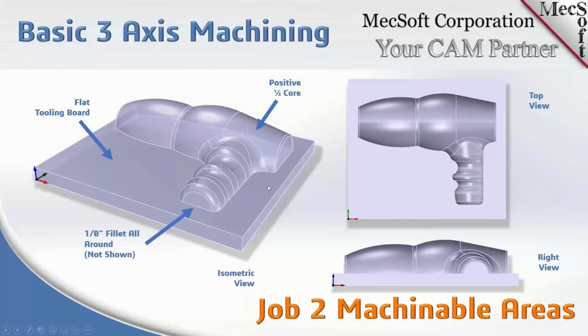And the reason that I selected this particular part is that you'll notice there's no fillet around the bottom edge. For vacuum or thermoform molds, you don't want to have a sharp edge. You want to have a fillet around there for the plastic to flow easily around. But the reason I picked this is that you don't have to model that fillet. We're going to show you how it's done in the machining process rather than in the design process.